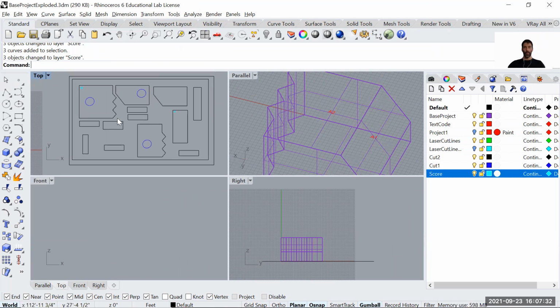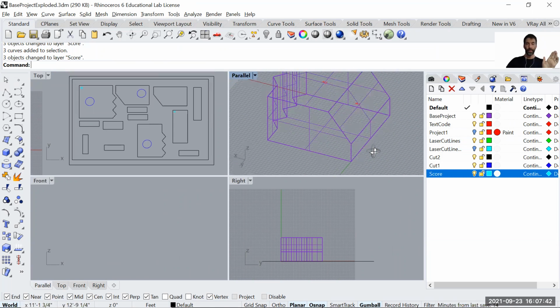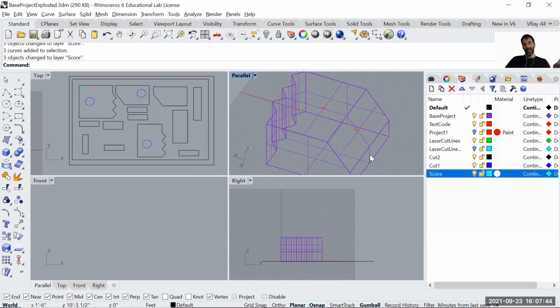It could be simpler, like 1, 2, 3, but each of the numerical codes has to be different for each of them, so you know by looking at the 3D model where they go. If it's a simple model, you can just let it be, no problem, and mount it by eye. But if it's a little complex like this one, you're going to want to know more precisely where each of those codes are. You will open Rhino, look at the numbers, look at the physical laser cutting result and then put them together accordingly.